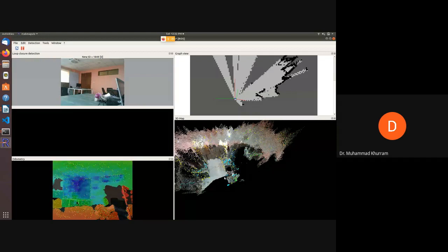Then is the filtering module of the vehicle. The filtering module actually filters the data and helps clean the raw sensor data, because whenever we are taking input from an environment, especially from our real-world environment, it's going to have noise, it's going to have bad values. So ROS again provides many libraries. Just to name a few, we have filtering libraries like Kalman filtering, EKF, extended Kalman filtering. We have UKF, unscented Kalman filtering. We have Madgwick filters for GPS values. We have IMU filters. We have Mahony filters.